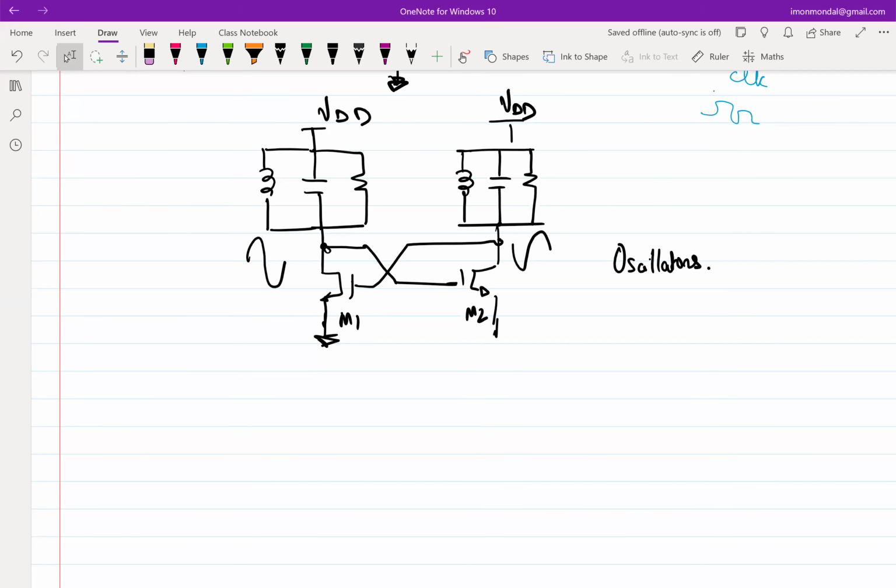So you have to use L, but once you have an L, don't tweak it, right? Whatever loss it gives, you live with it, but don't add more to it. The moment you try to tweak it, you are going to add something and it will mess up your circuit. So if L is out of bounds, once you have fixed an L, the only thing that you can change is the capacitor, right?